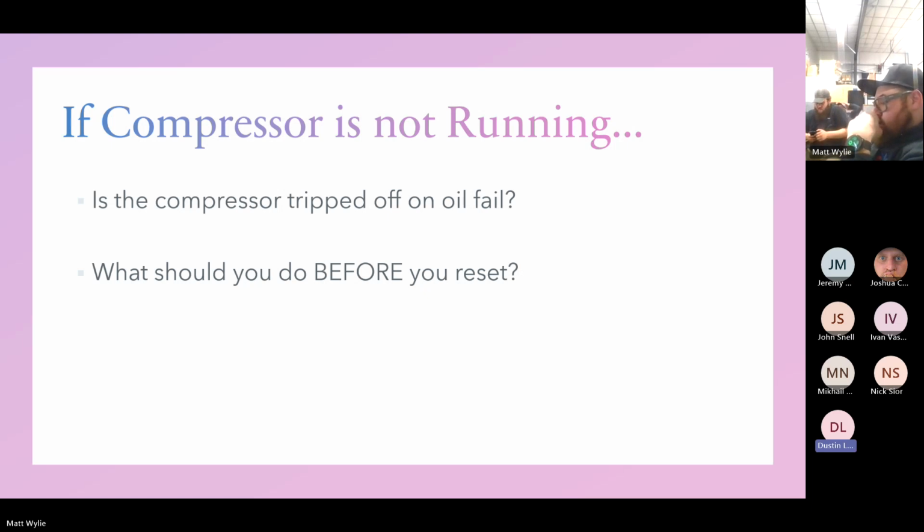So let's say we check our superheat at our compressor or suction header, and it's 15. Now you have to figure out which system is flooding back. If there's one system that's a ball of ice, I'm going to start with that one first. Then you go suction line to suction line, checking superheat. Anything below that 20 to 25 mark, I'm going to start with first, and then you have to go out and adjust all the valves for those. So floodback is a big cause of oil fails.